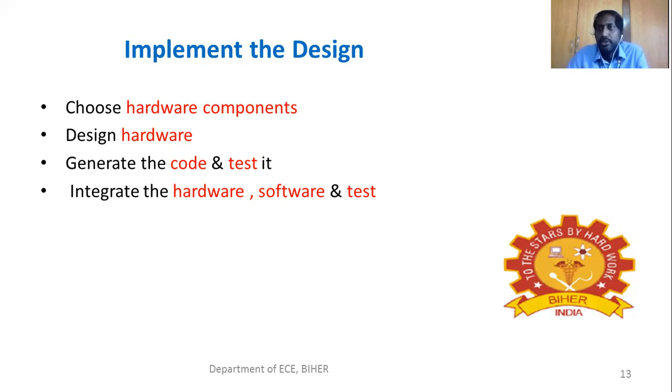Along with this, we need to know what size of memory is required. You need to analyze that also. It depends upon the application software. You need to choose on-chip memory accordingly, because compared with off-chip memory, on-chip memory is the fastest one. But the penalty we need to pay is that the price is high. So we need to choose the actual requirement of on-chip memory.